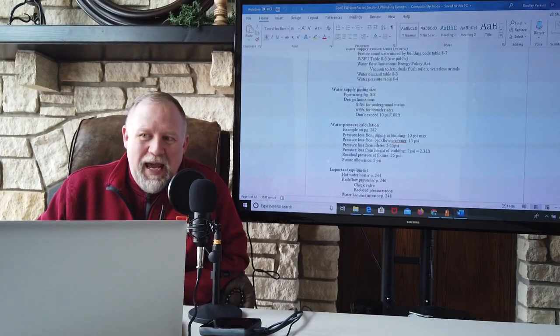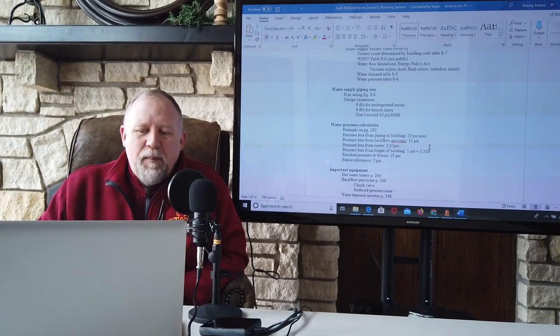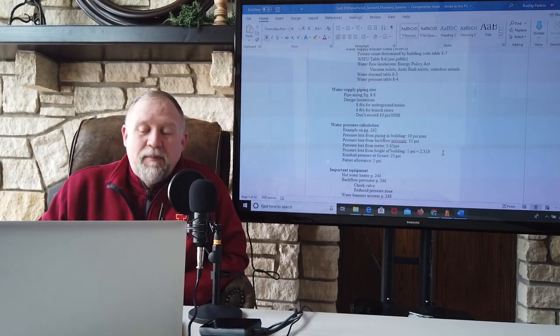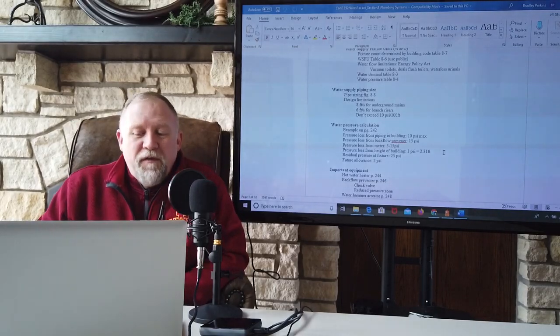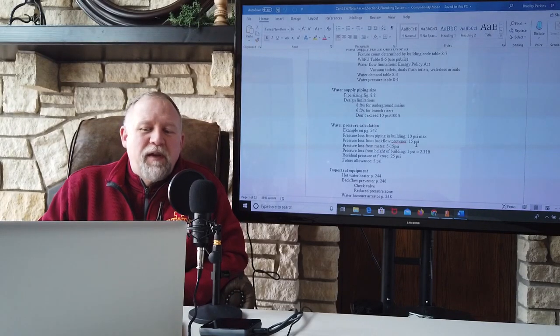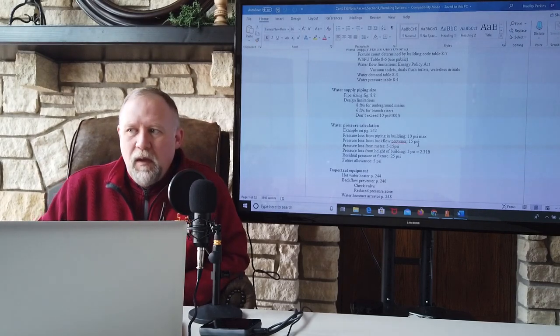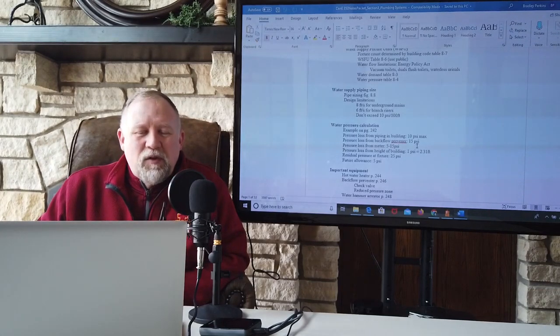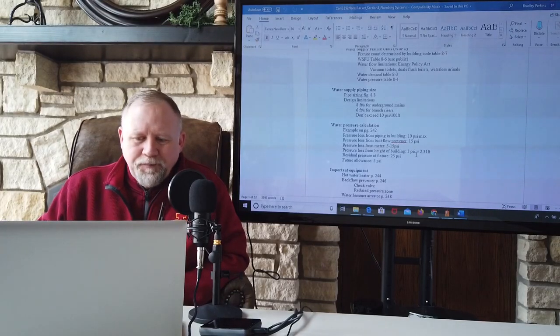In fact, you can. They do exist. But if I don't tell you, assume it's 15 psi, like on an exam or something. For your final project, if you need a lower pressure loss backflow preventer, you can use one. You just have to prove it by printing out a cut sheet from one of these backflow preventers. Watts Industrial, they make a lot of backflow preventers. That's where I would suggest that you start if you need a lower pressure loss backflow preventer.